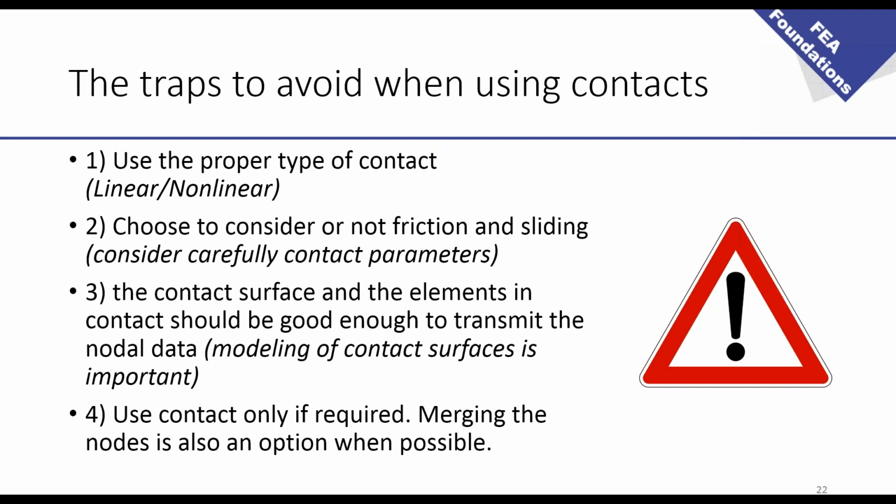And the fourth thing is that sometimes, instead of using contact, you can simply merge the nodes together. You have this possibility, you have to know it, that you don't have to use contact every time. In some models it makes sense to merge the nodes because you will get more accurate results and faster, because the software will not calculate the contact. You simply tell the software that the nodes are merged together, so it will consider it as one part.